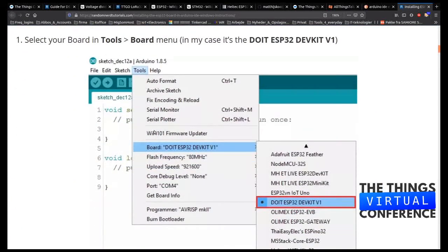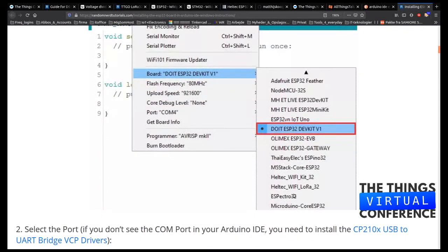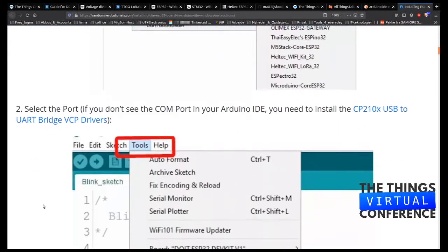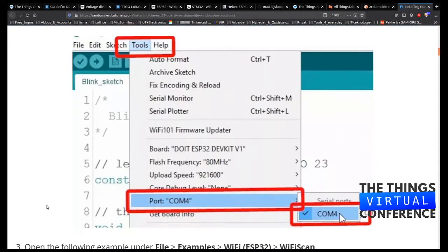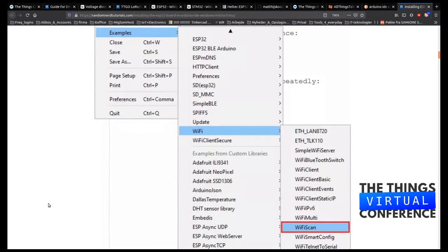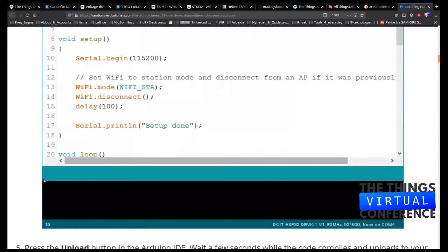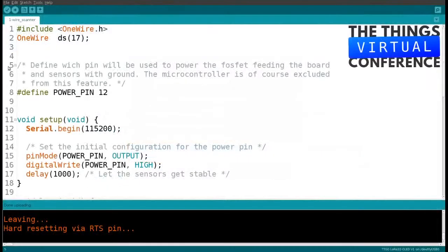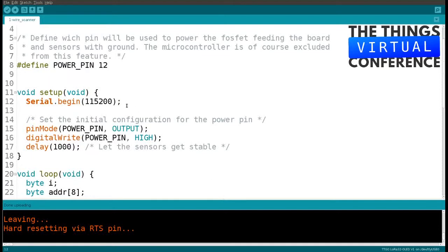You would go into Tools, Board, and on this list you will select the development board you are working with. For instance, a Heltec Wi-Fi LoRa 32 version 1, or a TTGO Wi-Fi 32. If you have selected that, then some other possibilities will pop up for selections on communication speed, etc. So that's how you install the hardware support and select the board you work with. It's a pity I can't show it to you, because my software right now doesn't show the windows that open when I push on it. But there are videos for that.